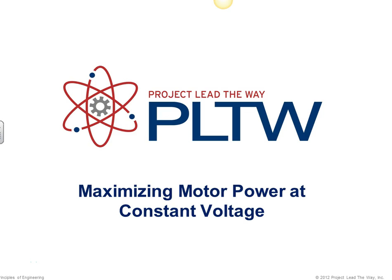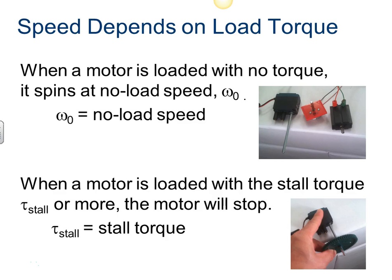This presentation is on maximizing motor power at constant voltage. So speed of a motor depends on how much load there is on it, and we would call that load torque. When a motor is loaded with no torque, it spins at a no load speed. If you can imagine an electric motor just spinning, connected to a battery, nothing attached to the shaft that's turning, it's just spinning as freely as it can. That would be called omega naught or omega zero, and that's equal to the no load speed.